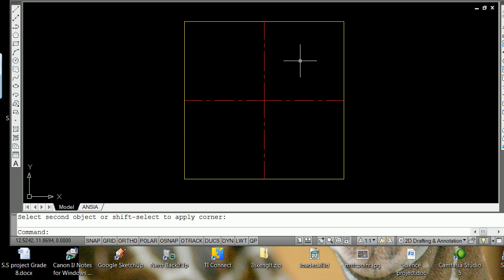In all reality, on this piece, the left-right lines are not that important, but I'll leave them on for just a while, and now we can get to drafting the piece. You draft a box bigger than what you want to draft, establish strong base lines and base circles, and what we need to do here is we need to copy and rotate this line 80 degrees.